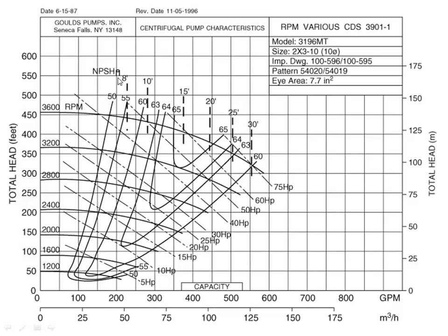And what it's referring to is the amount of head that's required in order to avoid cavitation. And the relationship is that as the flow rate increases, you can see over here on the right side of the curve, the flow rate is at its highest, more net positive suction head is required. And so we're going to talk about what that means, but the general trend I want you to notice is that for low flow rates, you don't need as much net positive suction head. There's less of a risk of cavitation at a low flow rate than there is at a high flow rate.